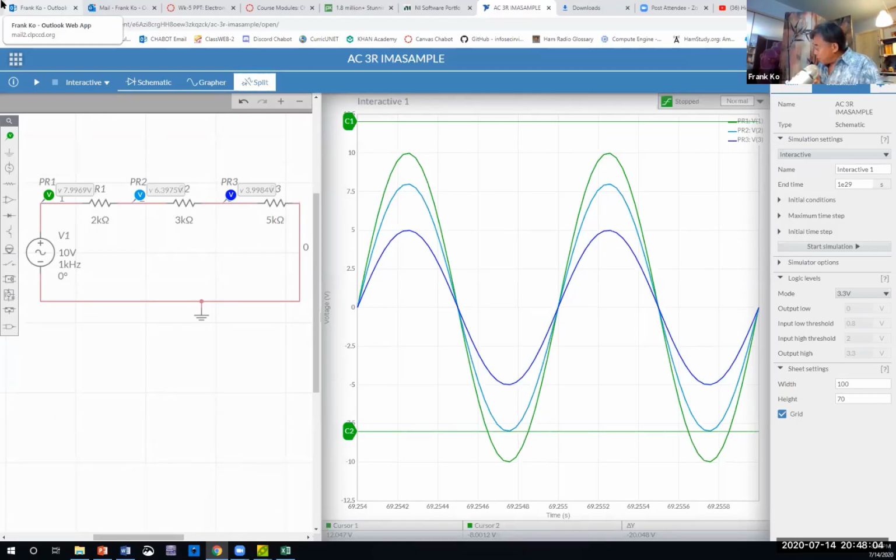And then it says that the wire diameter changes. So the wire diameter has now gone from 40 millimeters down to 2 centimeters. Well, initially your 40 millimeters had to be changed to 4 centimeters. And so the diameter went down by a factor of 2. But if you draw this out on a circle, the diameter changed from 4 down to 2. So the area decreased by a factor of 4. It's 1/4 smaller now.